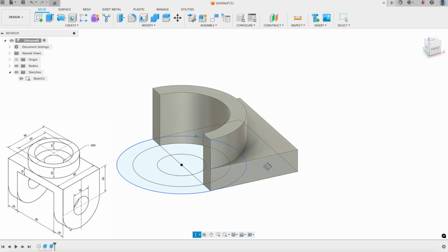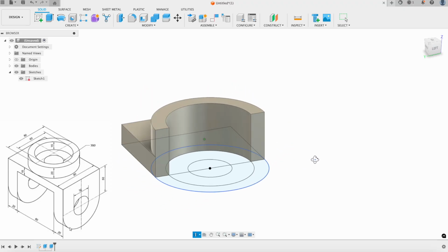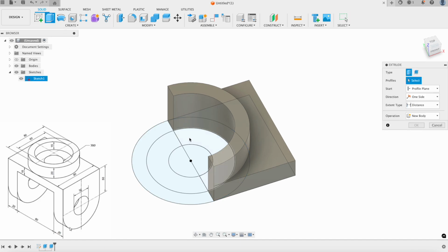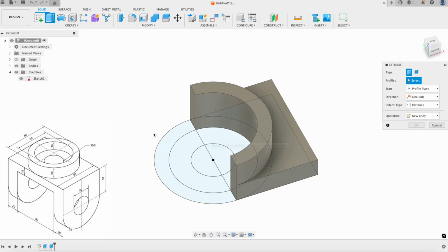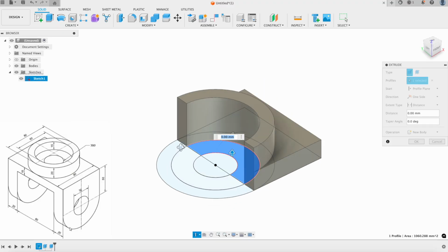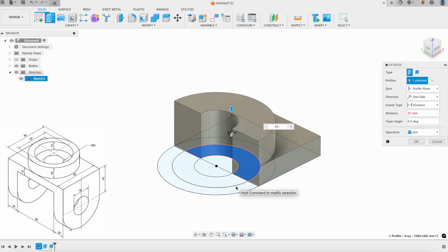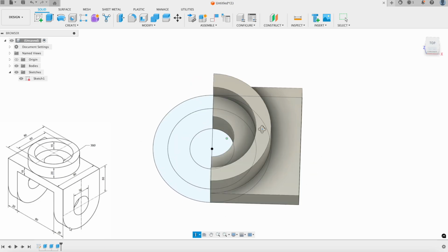Okay, so now going from the top, we could do this a couple of different ways. What I'm going to do is extrude one more time and then extrude this last little inner circle that we need. We see from the picture that if we were to go from the top of this lip, we want this to go 15 down from the top of that lip. So I'll click this, and we already know that the top of this is 35. Fusion just told us that, so we'll go 35, and now we can subtract 15 using our little Fusion calculator.